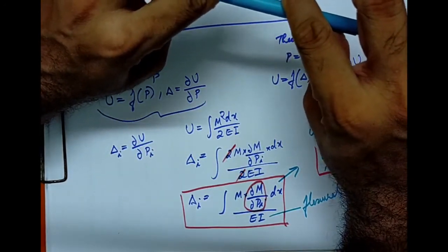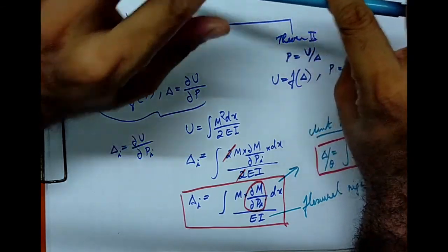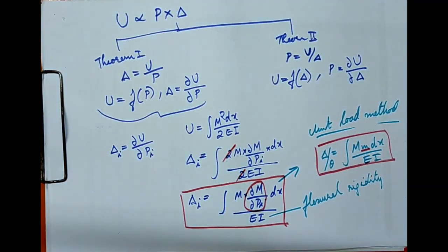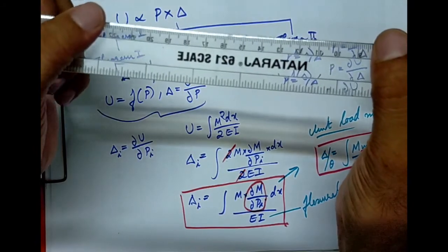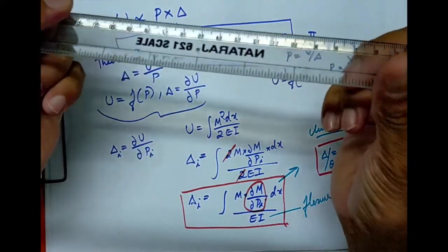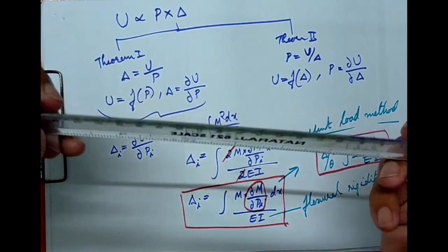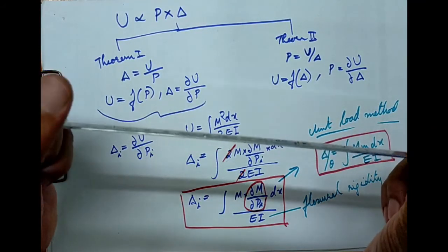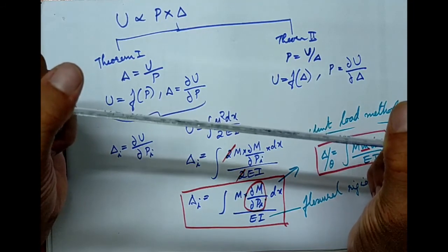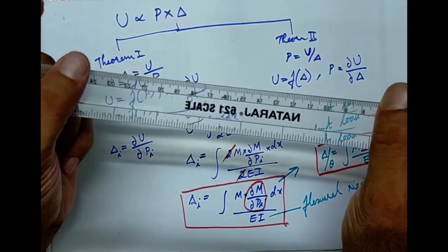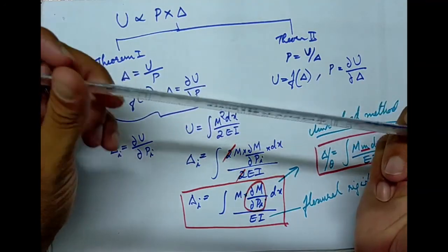And when we are talking about bending, when we are trying to bend something, the thing that comes into the picture is not the cross-sectional area, but the moment of inertia. We are very familiar with moment of inertia. Say if I'm having a scale like this, and I'm applying a force, when I'm placing the scale like this, it easily bends. The bending is pretty easy. But if I'm placing it like this, now it is very hard for me to bend. So even though I'm applying the same amount of bending moment, this one is not bending, but this profile is bending very easily. So what happened?